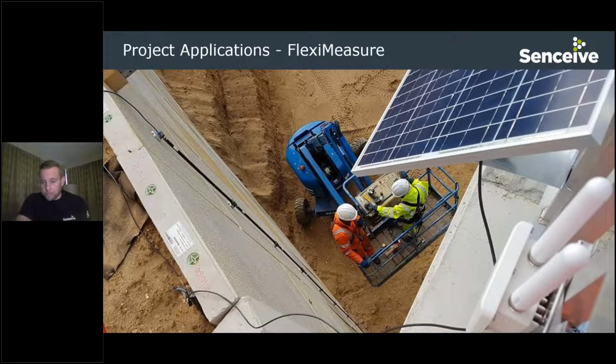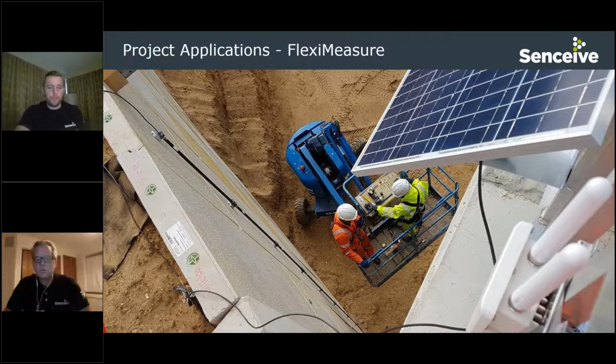And the fleximeasure. This one, as I mentioned earlier, can be installed on the face of structures to measure any lateral movement. It's available in different segment lengths from 0.5 meter up to 3 meter, all easily connected in the field, completely waterproof. These connect directly back into an Edge Hub data logger. That's what's shown on the bottom right here.